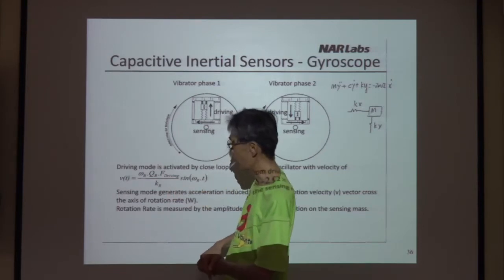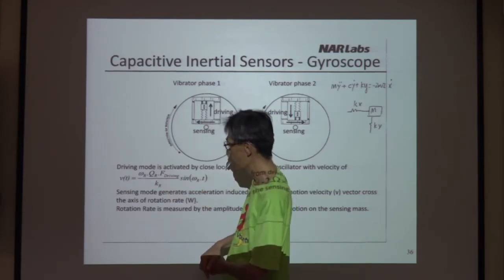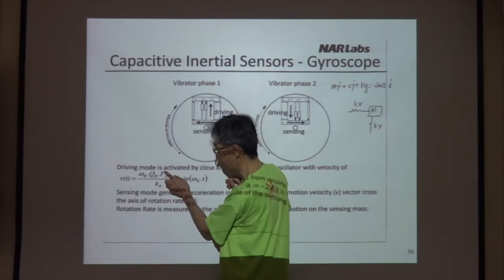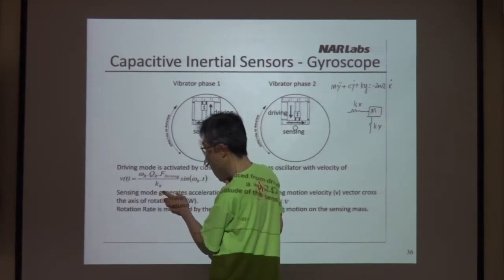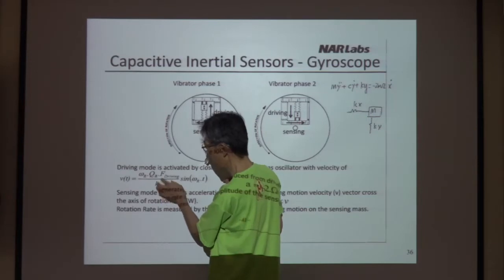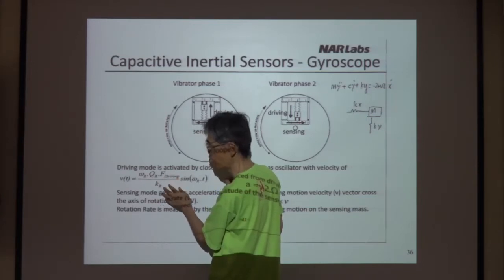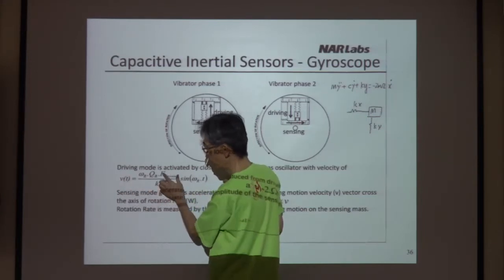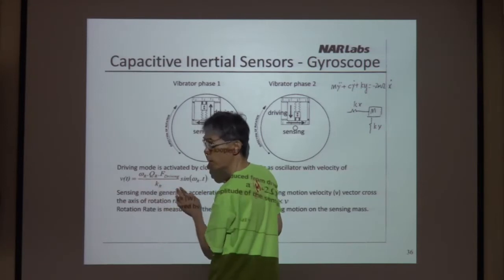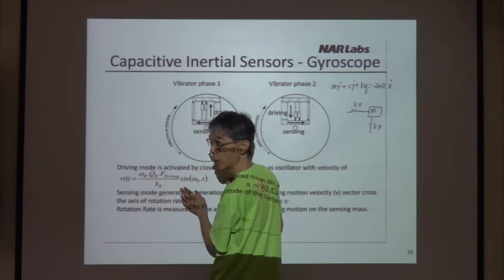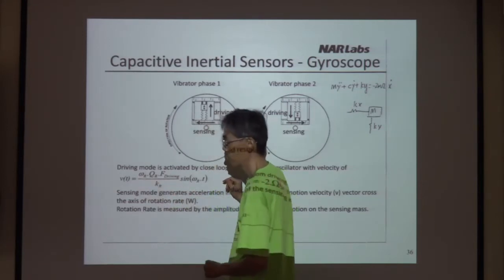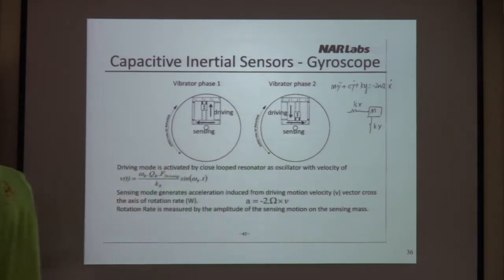Imagine the vibration amplitude equals F divided by k. That is the vibration amplitude, but this is speed. So F divided by k is the amplitude. The amplitude times omega is the velocity. We can show you some simple maths.